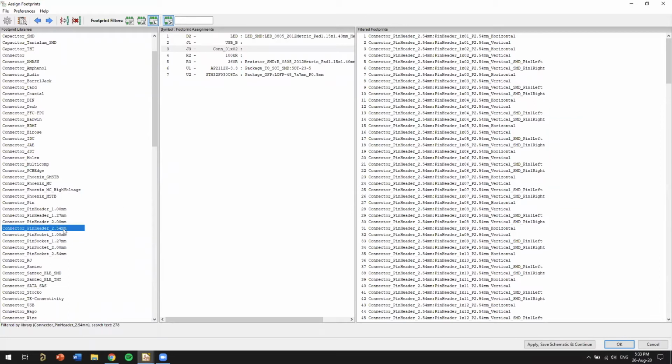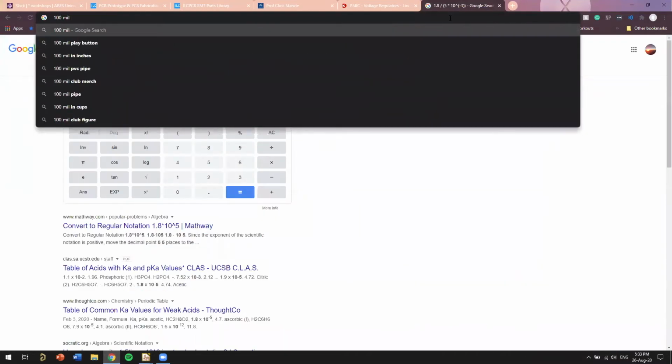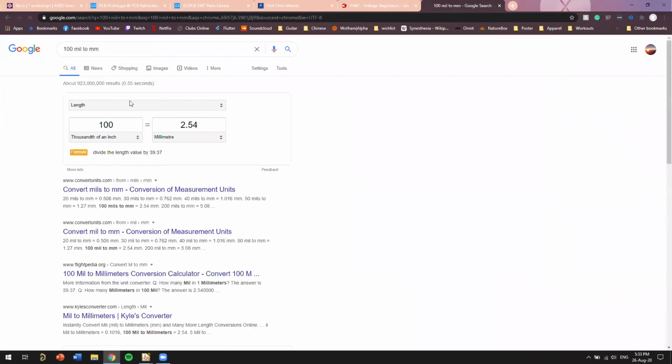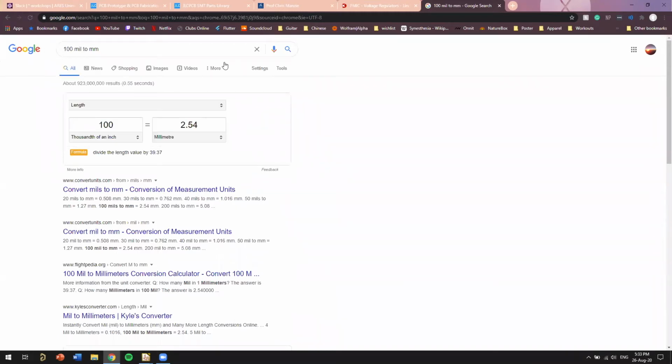2.54 millimeters is the pitch. Basically means it's the distance between the pins, and 2.54 millimeters, I think, is 100 mil. And when I say mil, this is something that you want to get used to in PCB design. A mil is 1,000th of an inch. A lot of manufacturers use mil to talk about the size of things. It's pretty standard. If you talk about trace width or distance between traces, you might want a 10 mil trace width or a 6 mil trace width.